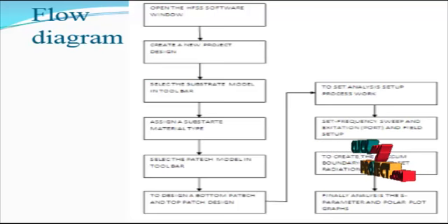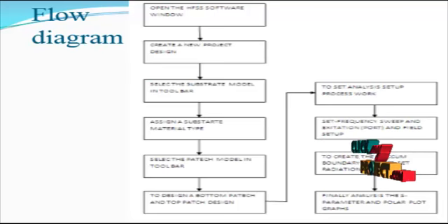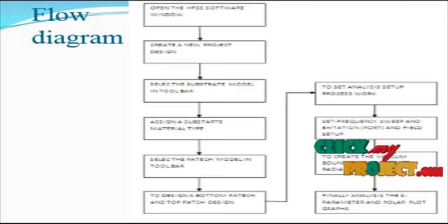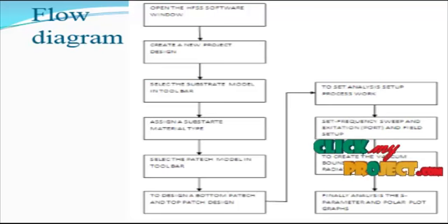The material represents a Rogers material, and we go to the patch model design. Whatever patch model we use, circular, square or rectangular, is implemented in our designs, using the polyline for rectangular shape cuts, and we add and subtract to implement the design, with the XYZ dimensions of the substrate model in our new project.